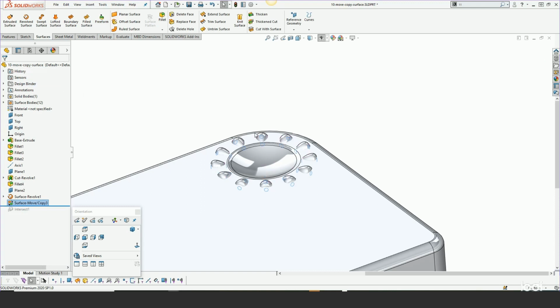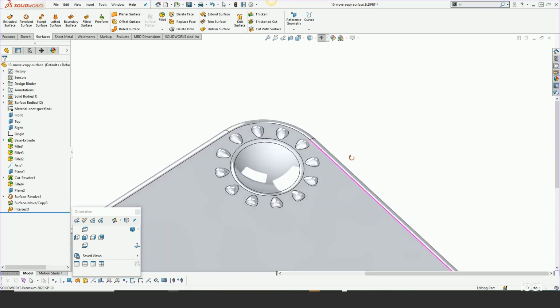So now I have a bunch of surface bodies sitting in a solid face, and then I can use the intersect tool. If you haven't used it, very valuable tool. And even though those are open surfaces, that they're not closed up, intersect can understand how to take those surfaces, combine them with the solid, and then make one uniform solid body.